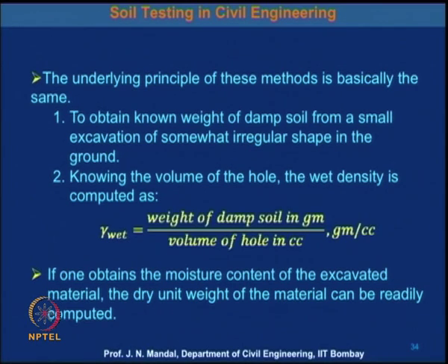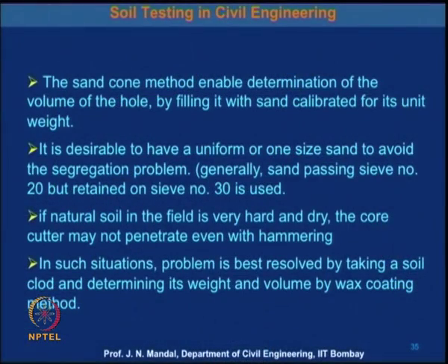If one obtains the moisture content of the excavated material, the dry unit weight of the material can be rapidly computed. So, if you know the weight density, you can also determine the dry density of the soil sample. Then the sand cone method enables determination of the volume of the hole by filling it with the sand calibrated for the unit weight.